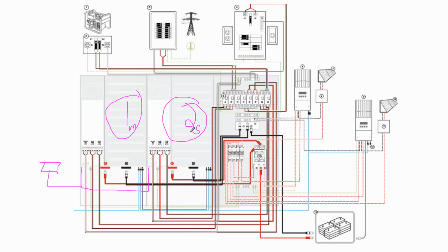Now, just a finer detail. If one inverter fails on you, if your master inverter fails on you, the slave inverter doesn't automatically turn into the master inverter. That might be something that more complex programming, such as the energy server, would do. But out of the box, generally, if something goes wrong with your system, the inverter company wants you to actually come out and take a look at it to see what's going on. So even in a double stacked inverter configuration, you don't have a completely seamless transition.